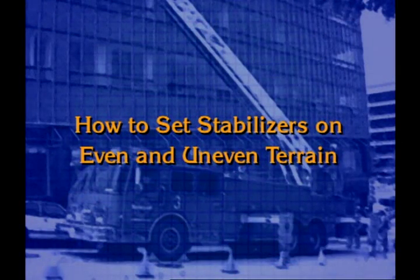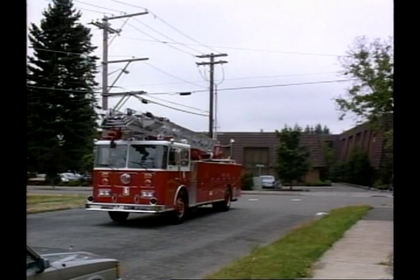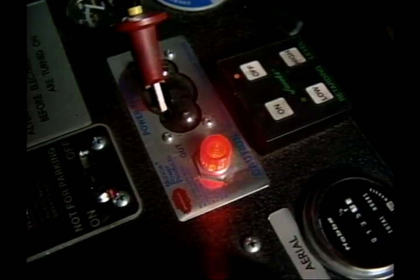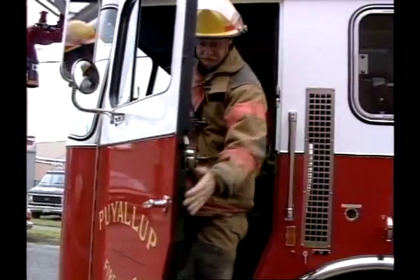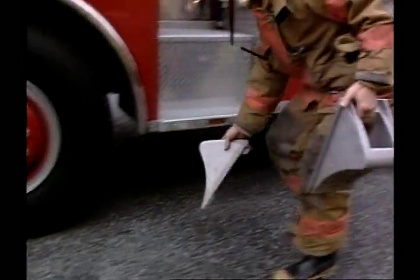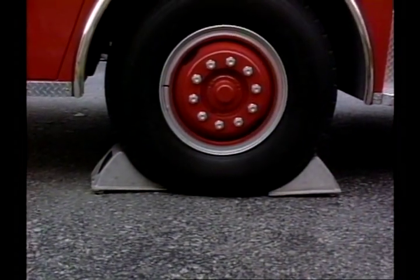Once the PTO system has been engaged, you can begin the stabilization process. Before actually deploying the stabilizers, there are several quick checks you should make to avoid potential problems. First, be sure that the PTO light is lit before you leave the cab. Second, some manufacturers recommend that you chock the wheels at this time. The manufacturer will specify whether the front or rear wheels should be chocked.